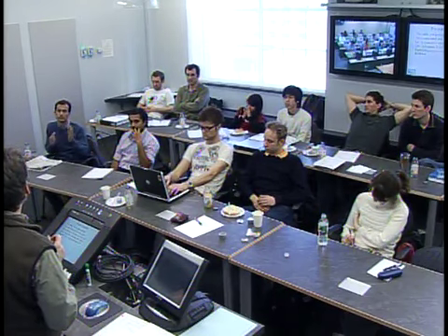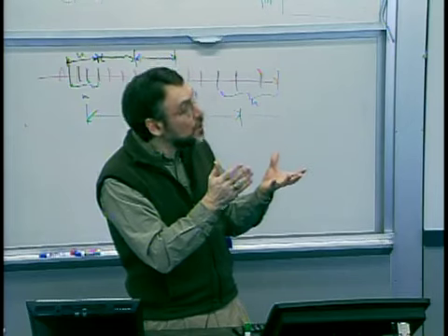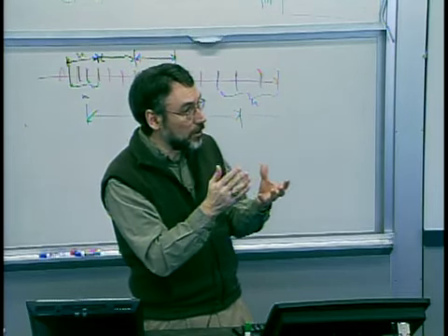Let's say length tracking between horizontal and vertical gate lengths would be very important, and each step by itself could be Six Sigma, and if the tracking is off, both could be within that limit. So that's again another multivariate question, looking at how important it is for two parameters to be close to each other, even if one or the other could deviate.